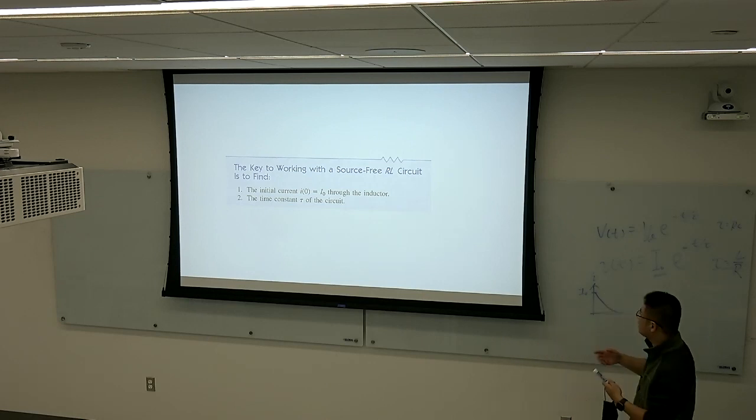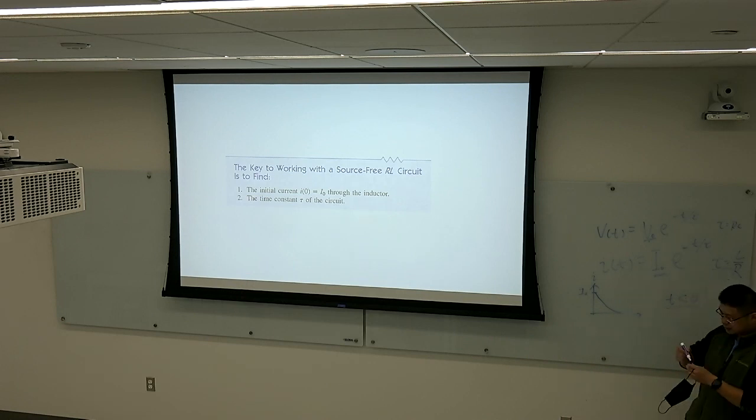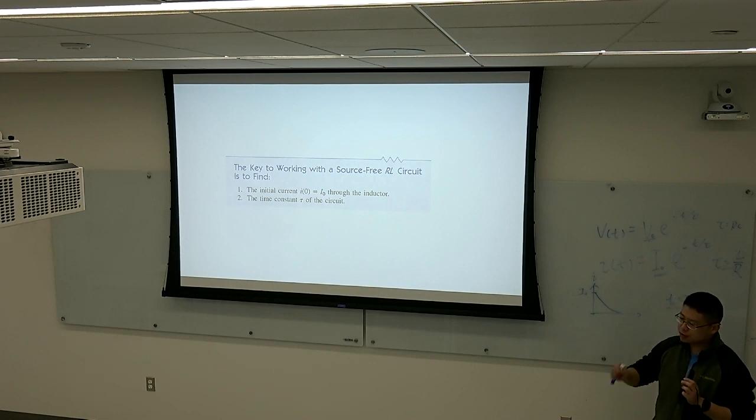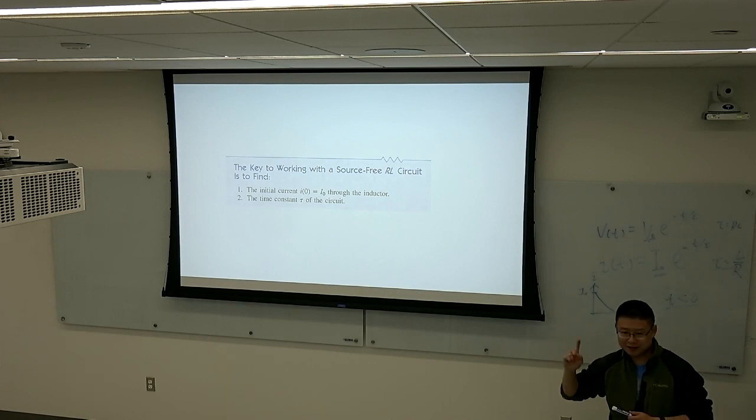That is the inductor current when t is less than 0. Assume steady state. In steady state, we treat the inductor as a short circuit or open circuit.